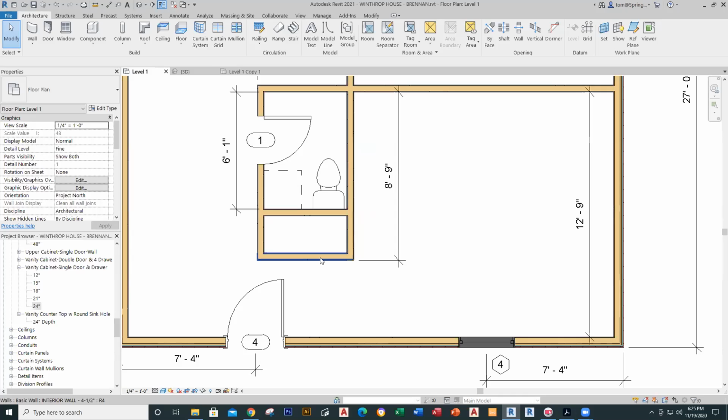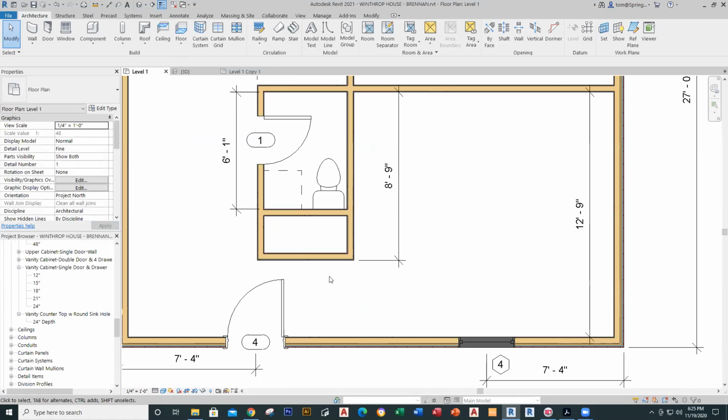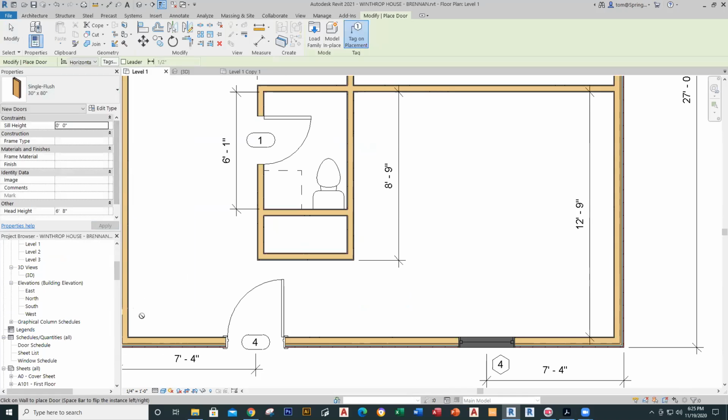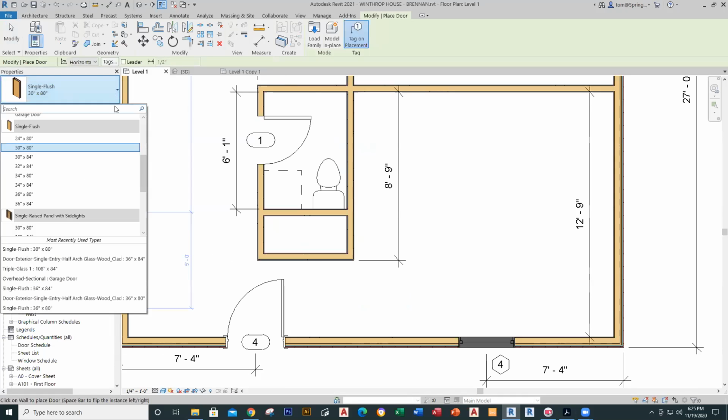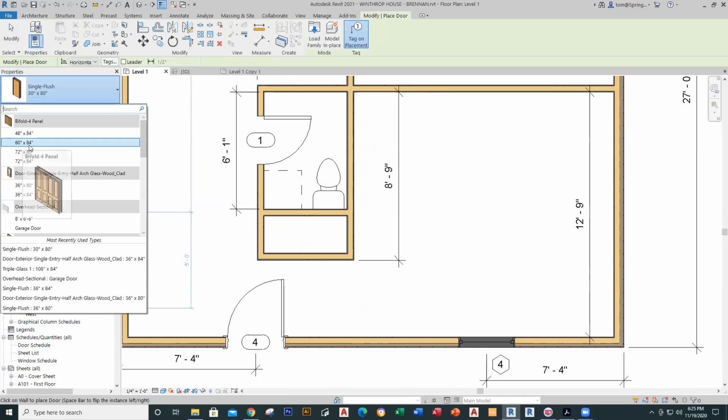Now, the next thing I have right here is a bifold door. The bifold door would actually get set right in the front here. That's number 2. Number 2 is a 48-inch by 84-inch panel, and all that can be found on your construction documents there. So I can go to my doors, and I'm going to go up to door, and I'm going to find that, which is going to be a bifold, 48 by 84. Let me find my bifold. There it is, 48 by 84.